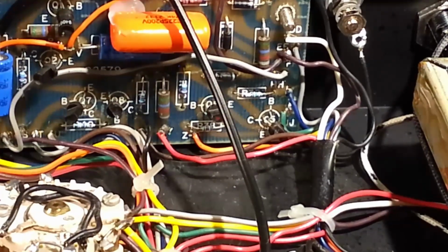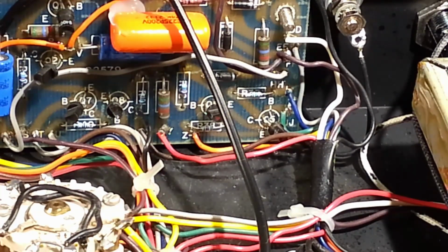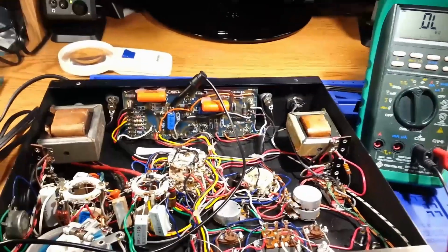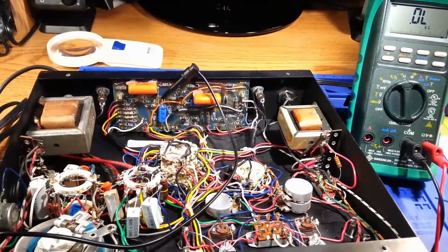I'll have to check that, but I'm going to have to go through the schematic and do a bunch of continuity tracing and relabel a good version of the schematic to get the proper continuity and signal path through everything, just because somebody didn't pay attention to all of the little markings between the board and the schematic that are supposed to match up in order to have a working and effective schematic.